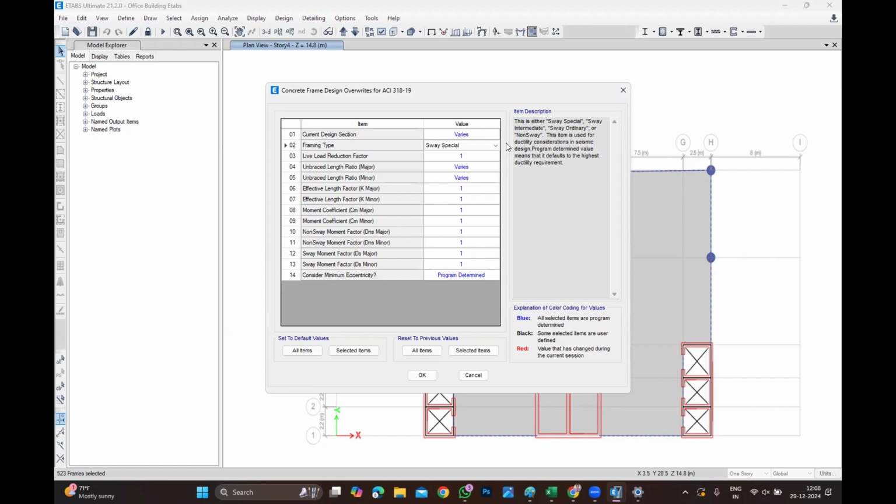The concept of floating column and planted column is the same. But when you talk in terms of reinforcement details, it is different. For the floating column, you're only taking the lap length. For the planted column, you have to take it to the base. If it is a slab, then you have to take it from the slab like an L bar. If it is a beam, then you have to take it like an L bar from the beam. It differs by how they are designing it.